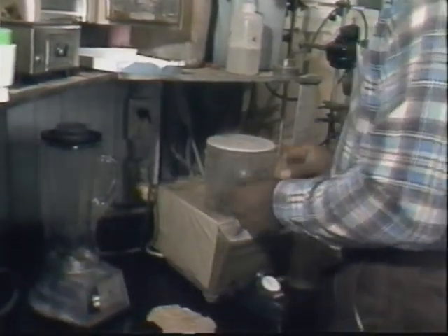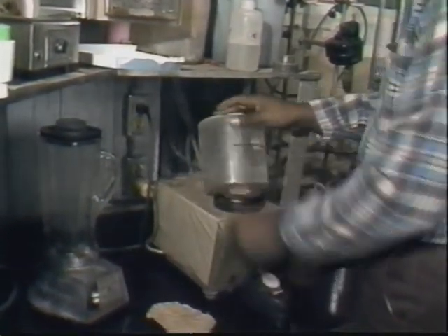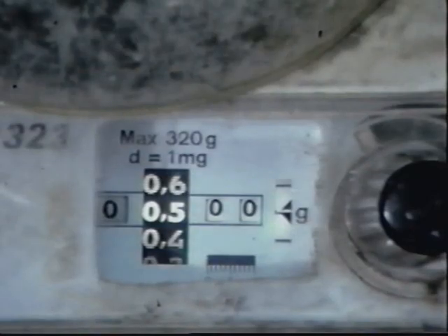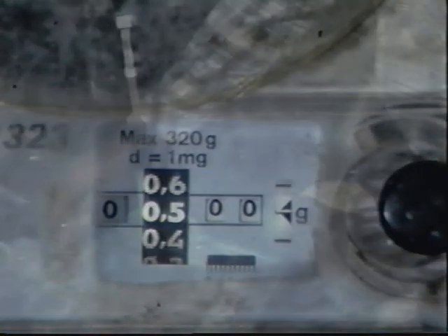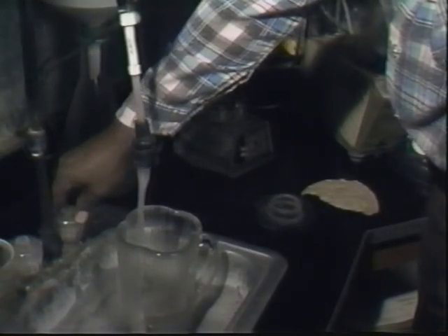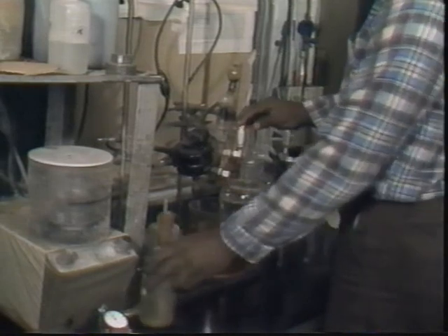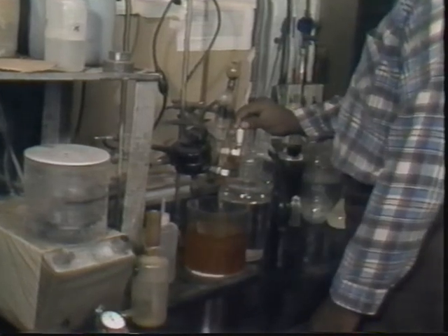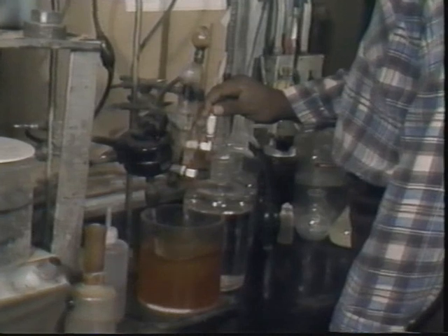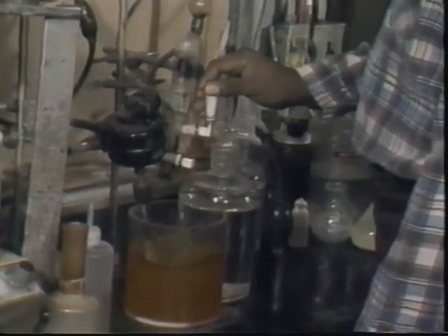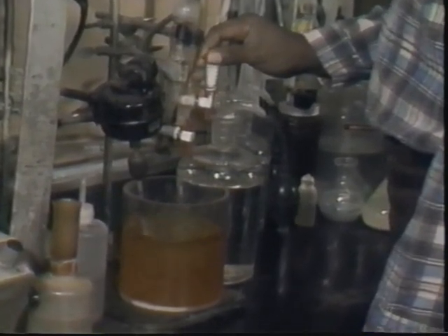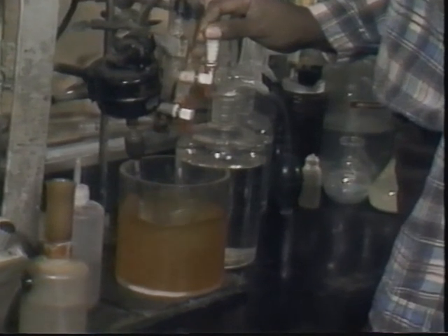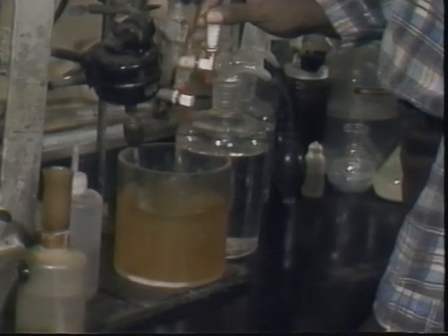This operator is conducting a K-number test. This test is applied to a sample of the pulp to determine the amount of cooking that occurred in the digester. A normal K-number reading means that the chips were cooked for the proper time and at the right temperature. A high K-number, however, indicates that the chips were undercooked, and a high K-number is consistent with a high debris level in the pulp. The K-number is found to be normal in this case, but this still doesn't rule out the digester as the cause of the high debris level.